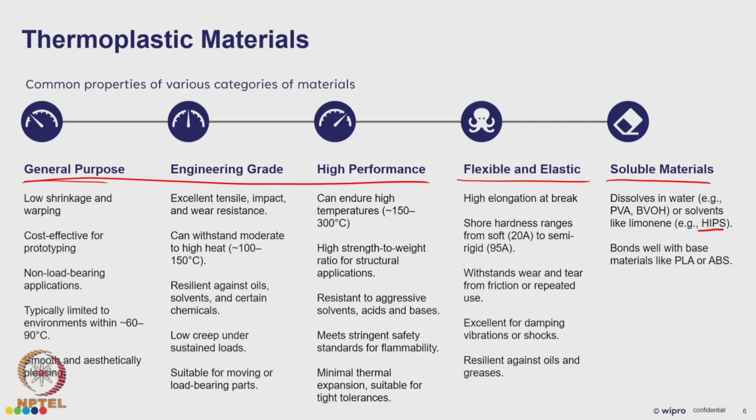This material bonds well with the base material, that means the model material like PLA or ABS, and it is also environmentally friendly and soluble in water or other solutions. We get very good smooth prints because it is easily removed and does not damage the model material. So this is a very good material when we want very intricate shapes, and it maintains its integrity until dissolution. That means it does not change its geometry until we move it to either water or limonene kind of solvents.